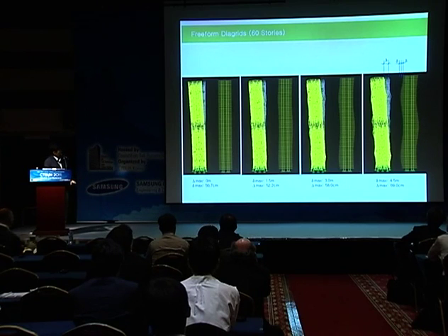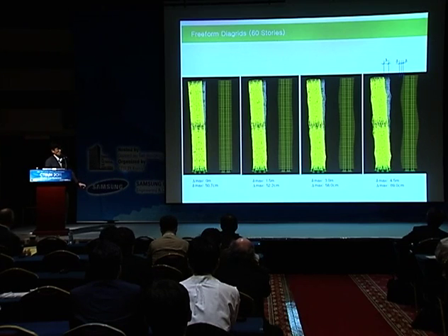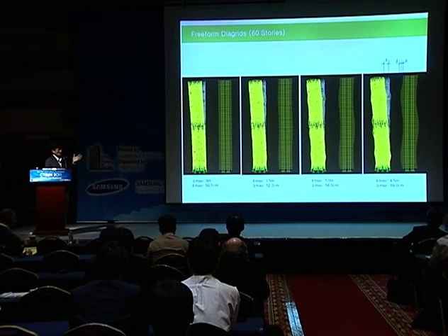That is shown as this plus minus delta, and this large delta is the lateral deformation. So the first case is the straight case, and the next one is the deviation of plus minus 1.5 meter. The second case is plus minus 3 meter deviation from the original box form. The third one is plus minus 4.5 meter from the original box form. And in this building case, the original box form building, the core perimeter to actual building perimeter is 9 meters. So the building form deviation is fluctuating from 0 to plus minus 4.5 meter in this case.